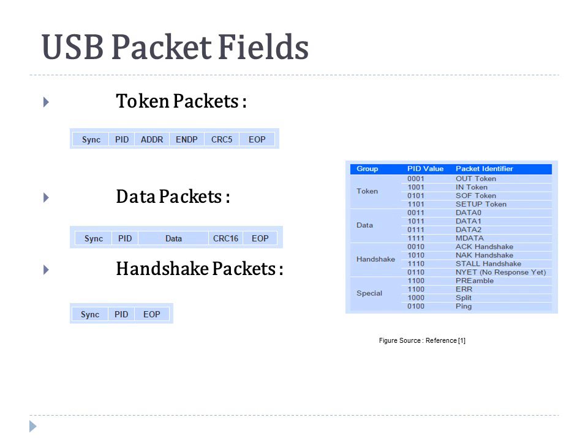So the token packets are sent from the host to define what kind of transfer is about to happen. So there are several kinds of tokens: out token, in token, SOF token, and setup token. So out token packet is used for an out transaction. Again, the out is from the perspective of a host, so it is the host writing data to the device. The in token is host reading a data from the device. Once the in or out token is sent, it is followed by the data packet, which includes the data and the CRC, and then the source of the data or the recipient of the data sends the handshake packet with the status.